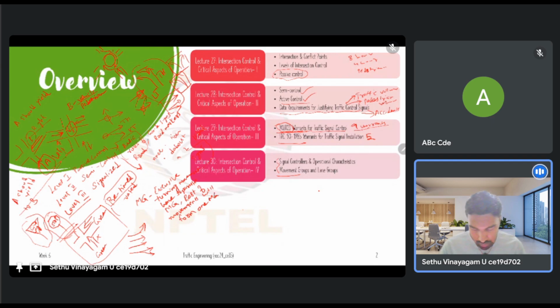What do we mean by exclusive left turn? Which means that in this particular lane, in the extreme left, we have only left turning movements happening from that lane. There is no other movement that happens from that lane, which means this is an exclusive left turning lane. So according to the movement group rule, this should be movement group 1. It is a separate movement group. And then looking at the rest of them, here these two are through movement.